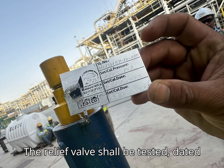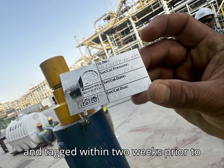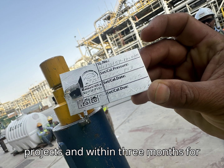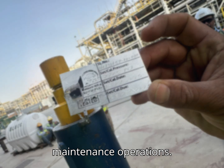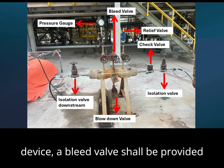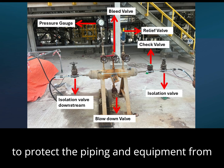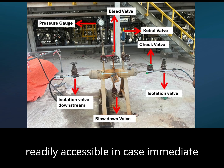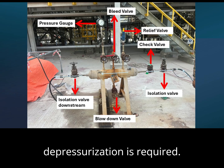The relief valve shall be tested, dated, and tagged within 2 weeks prior to the pressure test for new construction projects, and within 3 months for maintenance operations. In addition to the pressure relieving device, a bleed valve shall be provided to protect the piping and equipment from overpressure. The bleed valve shall be readily accessible in case immediate depressurization is required.